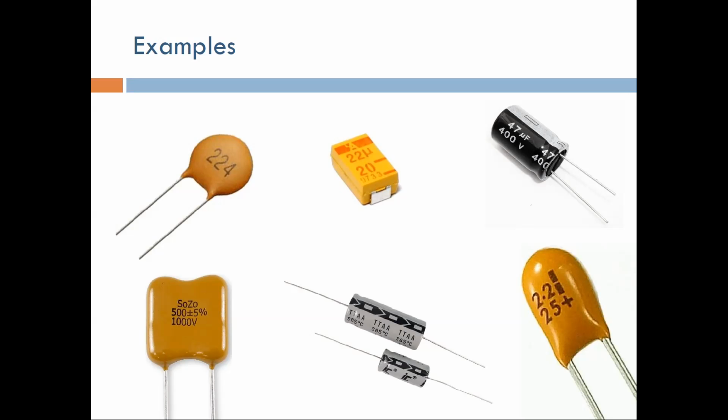Doctor, even if it was a high voltage capacitor, if I may. No, actually it was just a regular capacitor. It was a 25 volt rating, and if you put it in the opposite direction, it's not made to pass current in the opposite direction. So when you do that, the chemicals inside are just going to explode, because you're passing current in the opposite direction. It's not made for that, and this can be a problem.